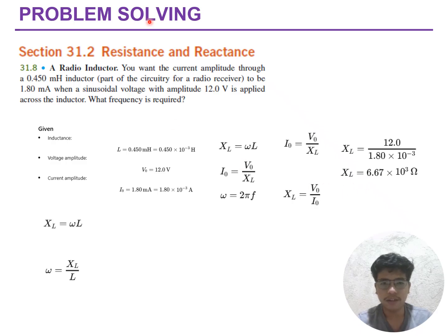Then after, we need to relate the reactance to angular frequency. Inductive reactance depends on angular frequency. So solving for angular frequency, we need this formula. After that, all we need to do is simply substitute this one into this one, and L into the other one on the bottom part. Then after we substitute, we need to convert angular frequency to ordinary frequency using this formula.